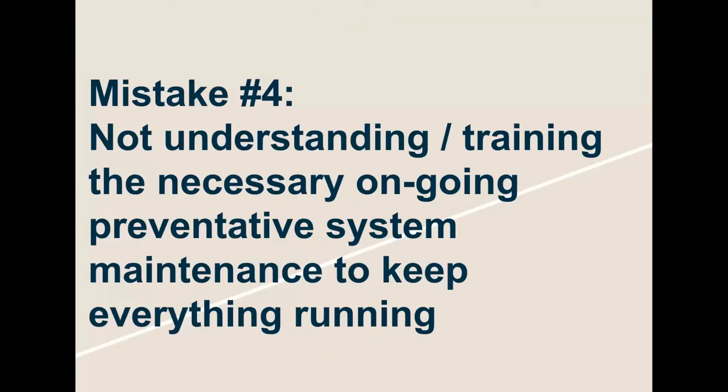Mistake number 4. This one is certainly one that I saw probably about 8 to 10 years ago. I was at an industrial gas customer, and they said to us that they test their system, and it was 150 plus sensors, plus all the lights and horns and controllers, et cetera. We test our system once a week with full bump testing on every single sensor. And as we started to drill down as to why they did this, they couldn't really say other than, well, it was the corporate policy, and we have to do this. And yet they were complaining bitterly about all the time that they needed to do it.